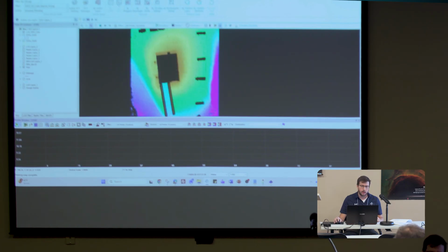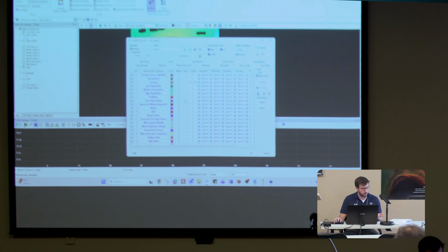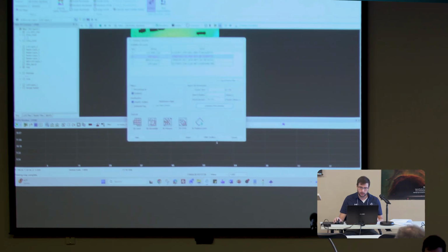Okay. And then I'll go back to our classification tab at the top, click outliers, go to LAS layer 2, input points filter. I'll filter by synthetic points, what we just did. Click OK, click OK. And now let's estimate the point density.